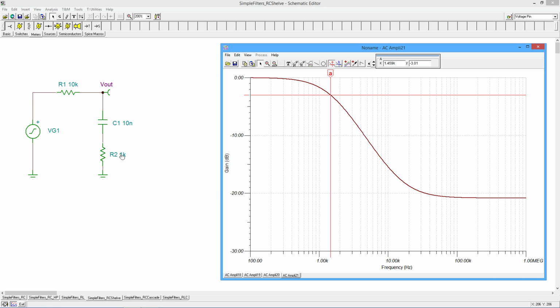You could put a resistor pot here instead of just a simple resistor, and you could get a little bit of control, but that would also do a little bit of the frequency shifting I was talking about. And there are active ways of doing that to have the shelf change where it hinges, and to actually have boost as well as cut. We can look at that with active devices like op amps. But this is a nice little variation, okay?